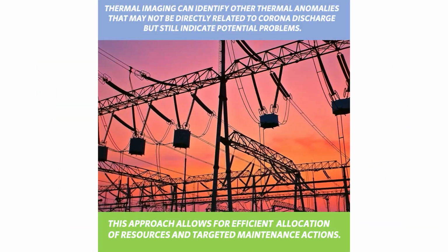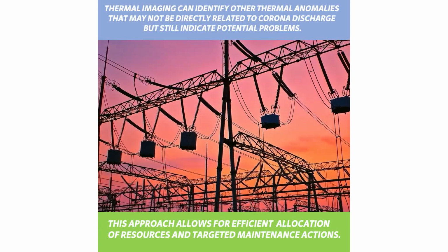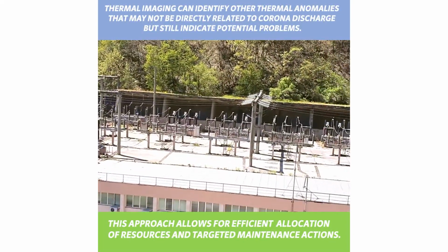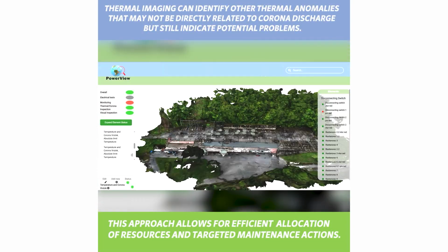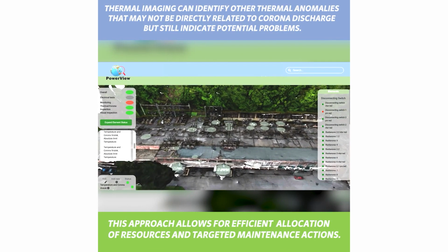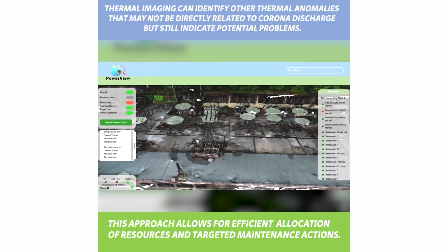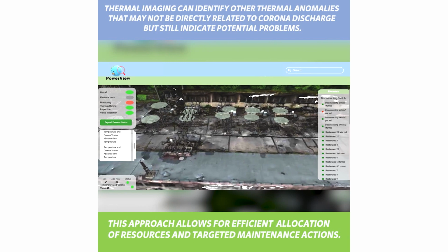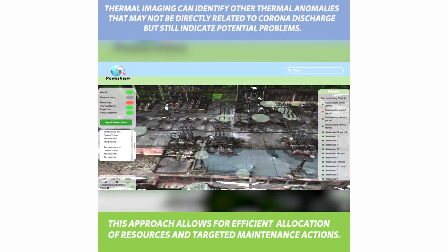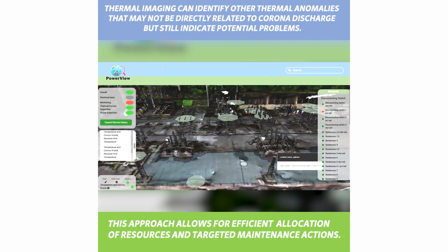The PowerView Complete Substation Thermal and Corona UV and IR can monitor all substation elements such as cable joint, knife contact, high voltage switchgear contacts or copper platoon connection point, cable connectors, copper connections, switch contacts, reactors, capacitors, arc suppression coil, insulators, VTs, CTs, power transformers, circuit breakers, bushings, insulators, etc. The temperature and corona on each element are trended individually so faults can be detected in the earliest stages.